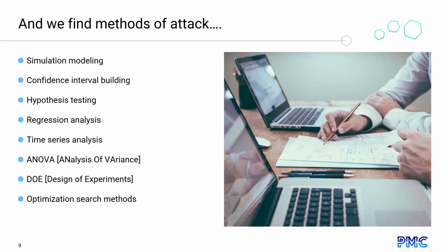So for example, pick a number, a preventive maintenance, tear down, check everything, like an aircraft engine, for example, after 600 hours of operation. So that's standard, built-in, baked-in policy.